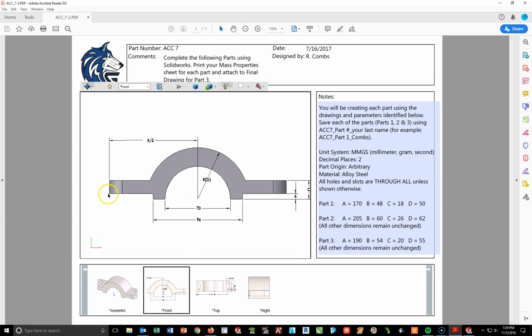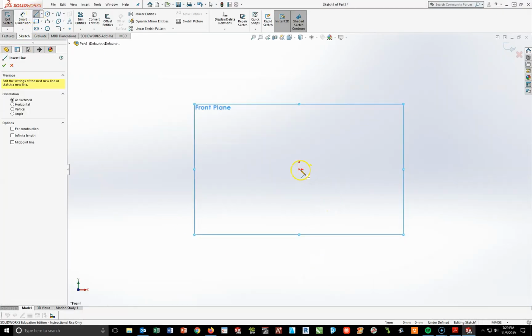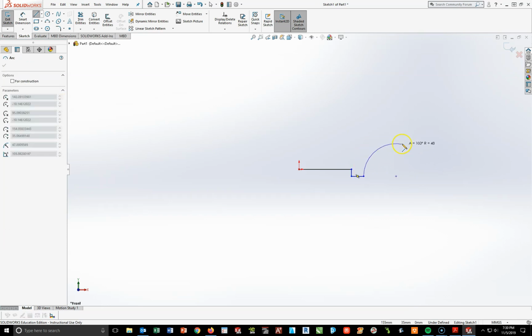So I'm going to draw a straight line over, down, over, and then I'm going to use my little trick to create this arc. I'm going to draw a line over, up, over, use my line trick again, come back over and close this. So going to SOLIDWORKS, I'm going to take my line tool, start out this way, down, over. I'm going to do the trick, which the trick is pull away, touch, and create an arc.